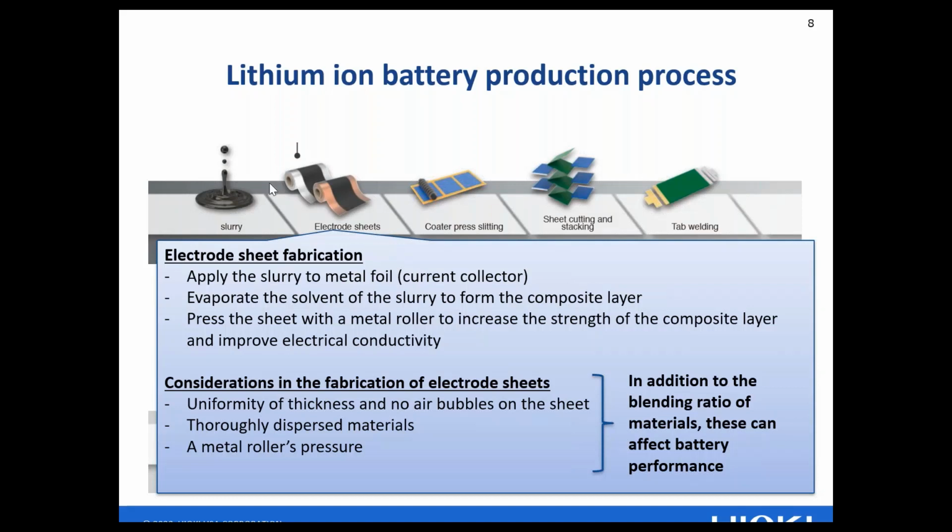The slurry gets stirred. The materials need to be well dispersed. You don't want to have any hot spots or bunching of materials anywhere. You want to have a uniformly, isotropically distributed material. And any mechanical engineer knows that it sounds pretty trivial to roll it with a metal roller, but a lot of things can happen when you have a metal roller hitting some gooey material. So again, a lot of potential failures in the very early steps of the battery processing.